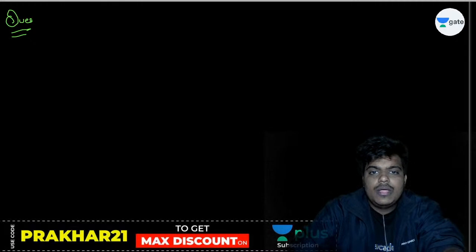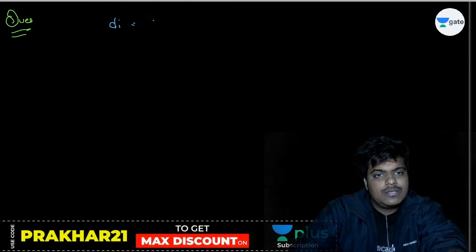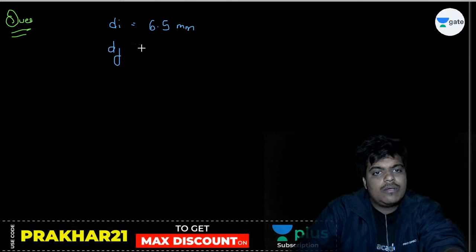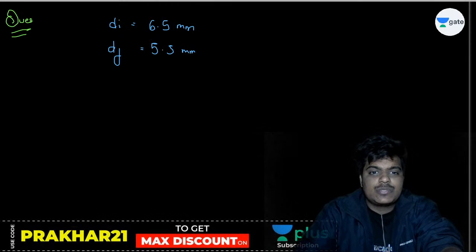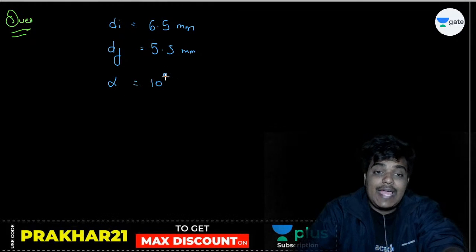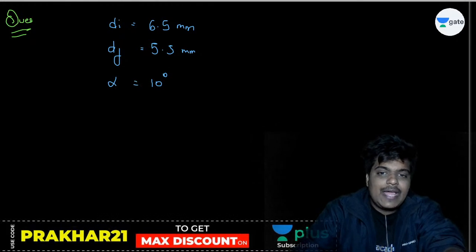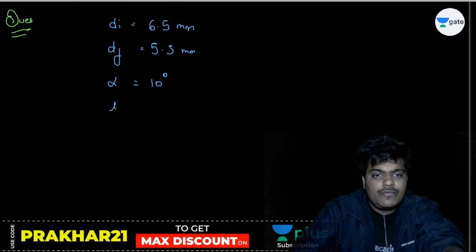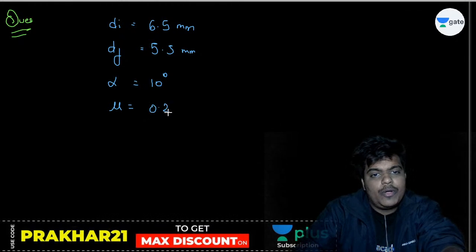तो लिखो. Determine the drawing load and maximum possible reduction when the initial diameter of the wire is 6.5 mm. The final diameter of the wire is 5.5 mm. This is an IES question. The semi-die angle is 10 degree. Die angle is 2 alpha, the semi-die angle is alpha. The coefficient of friction mu is 0.2.